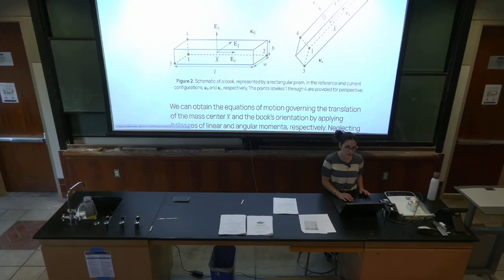E3 is greater, right? And I have the minimum moment of inertia mass distribution about E1. So these moments of inertia are ordered lambda 1 is less than lambda 2 is less than lambda 3. Make sure your neighbor is okay with this ordering of the moments of inertia. Any questions so far?